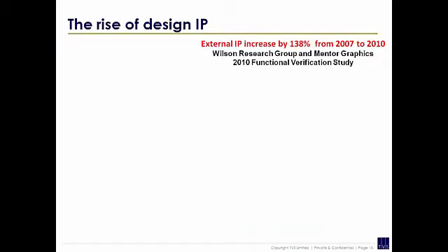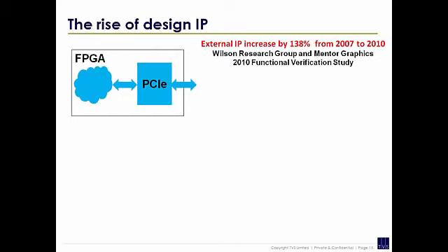So, some other advanced verification techniques people use. On the FPGAs that we work with, we're starting to find what we would call hardened IP. Do any of you use FPGAs with an ARM processor on them? It's hardened: you don't map the ARM onto the FPGA. The FPGA comes with an ARM embedded in it, already in silicon. We call it hardened IP, or embedded IP.